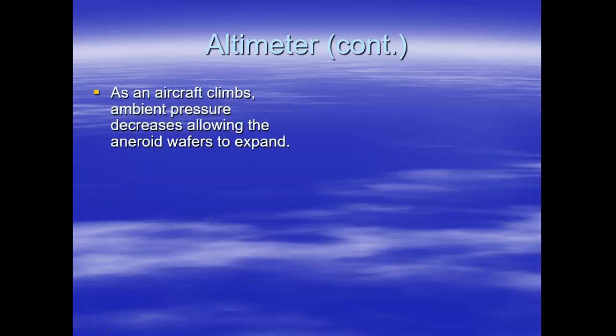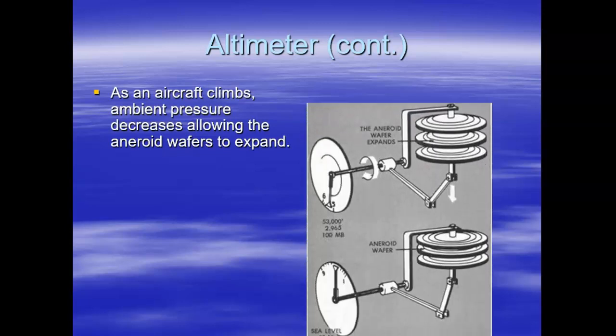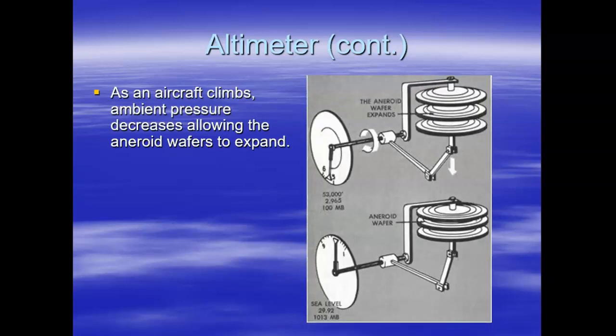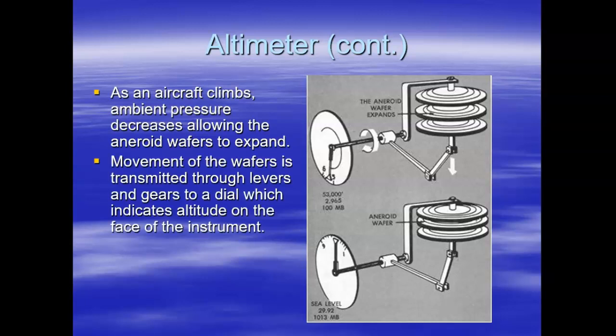As an aircraft climbs, the ambient pressure, the static pressure, decreases, which allows the aneroid wafers to expand. The aneroid wafers are attached to some levers and gears which drive the dial on the face of the instrument to show the indicated altitude.